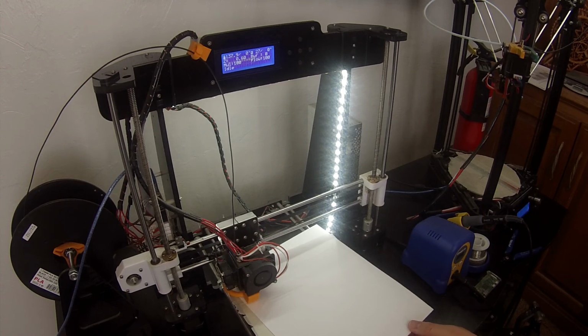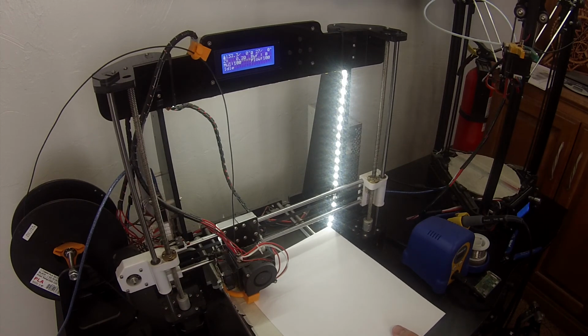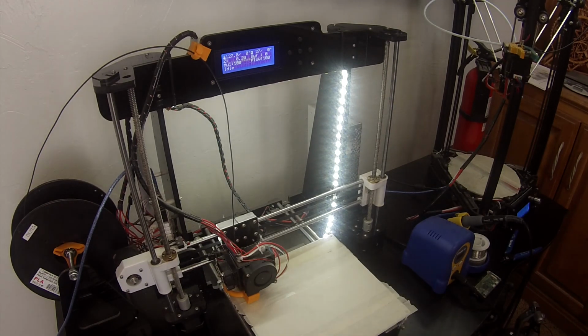Still not pinched. Don't feel any drag yet. There it is. There's the little bit of drag from the print nozzle head touching, and this occurs at a Z height right now. It says of 0.2 millimeters. So what I want to do is adjust the screws, which is usually the easiest path.